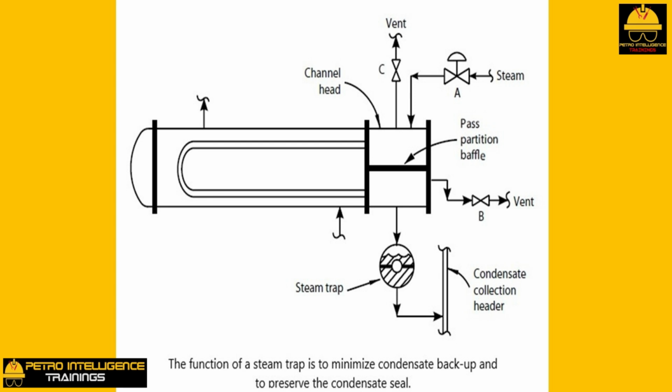For larger steam flows, we would use a condensate pot and level control valve, LRC, as discussed in the following section. The steam trap neither aids nor retards condensate drainage, unless it is mechanically malfunctioning, meaning it is sticking either open or closed. Also, replacing the steam trap with a condensate drum and LRC also neither retards nor aids drainage. Condensate drainage is a function of system hydraulics.